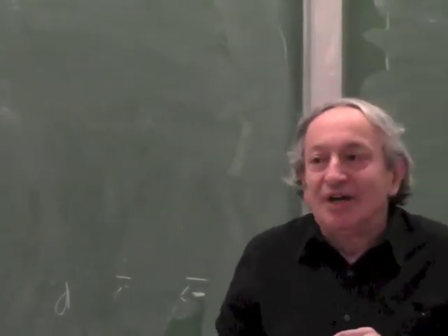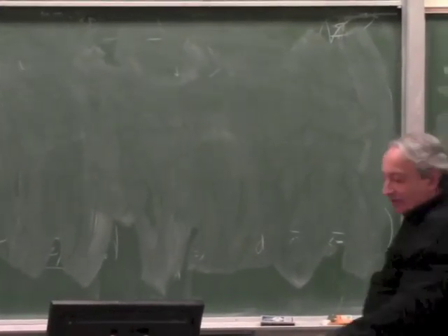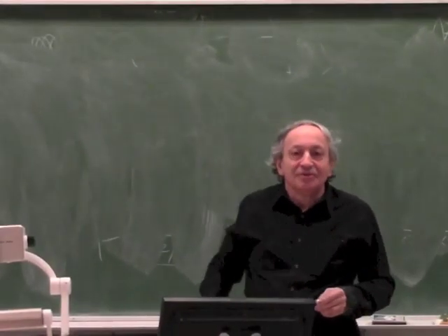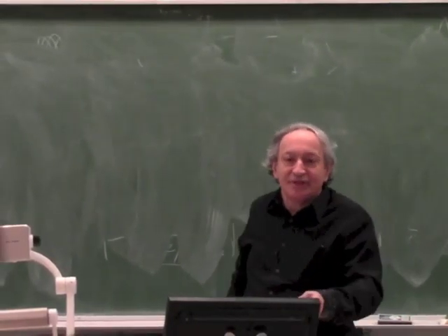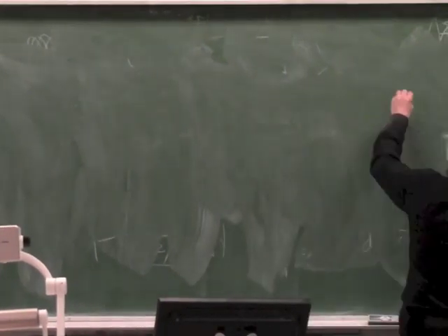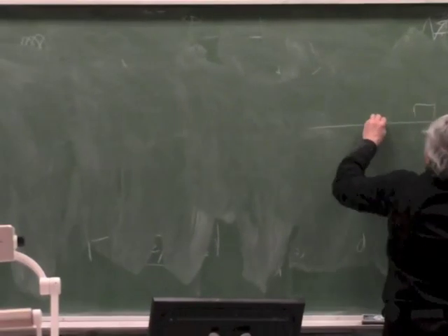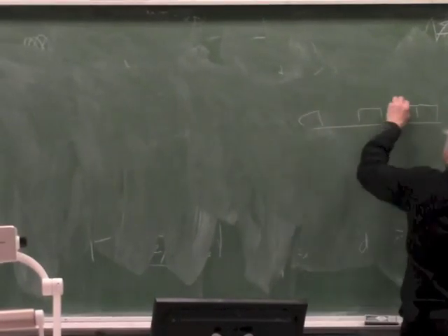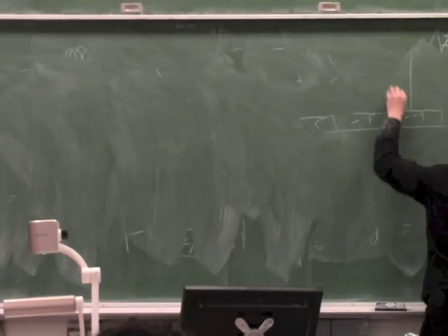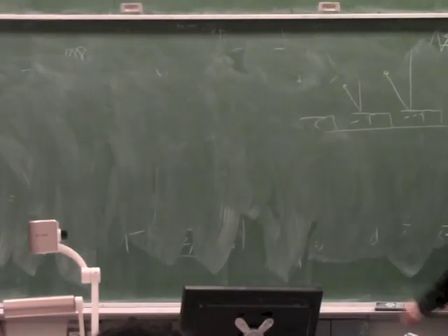Because of the snap, you cannot use it to modulate the light in a linear way. It was originally used for TV, and TV is analog, so each of those mirrors you wanted to tilt to modulate the reflected light.